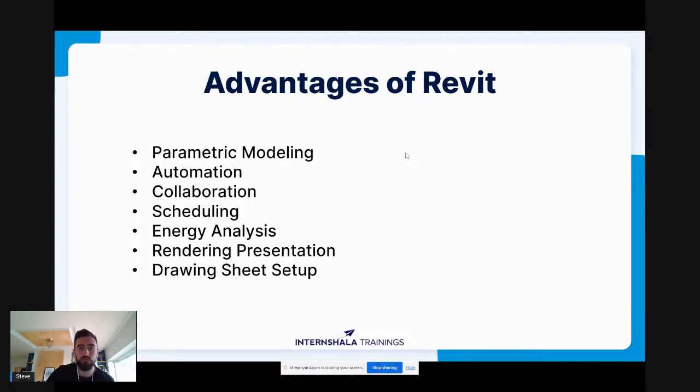A good, powerful advantage next is scheduling. In the same vein as a Revit model functioning as a single database of all information in the model, scheduling in Revit cuts down on the time traditional workflows demand. As changes are made in the Revit model, schedules that have been set up will instantly update as well with those changes, streamlining one of the more time-consuming processes in the architectural design process.